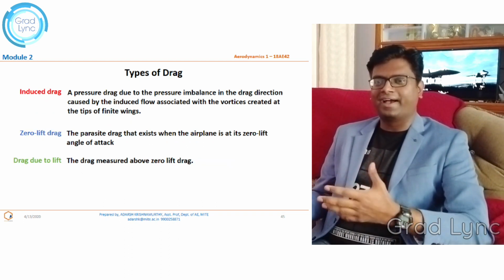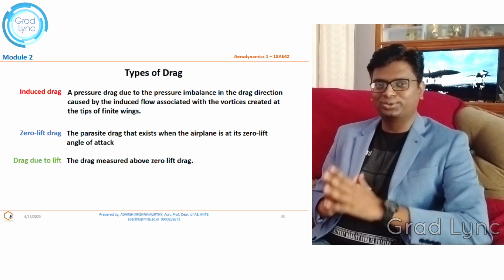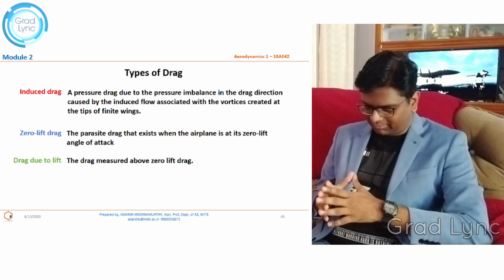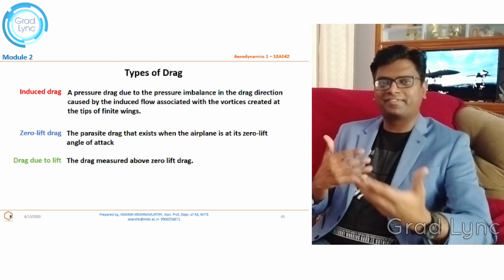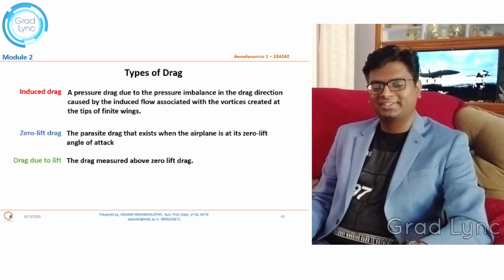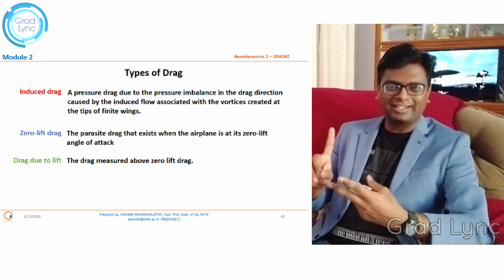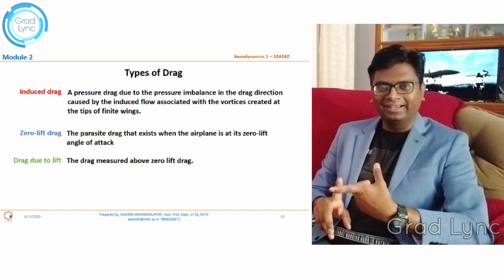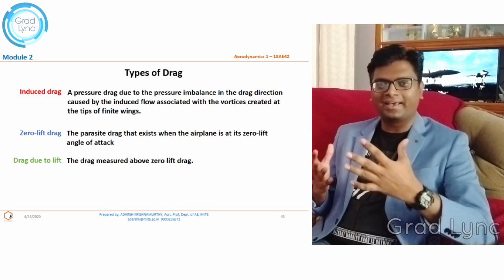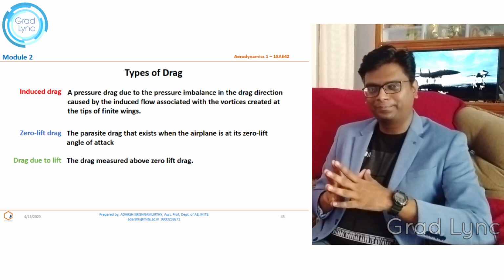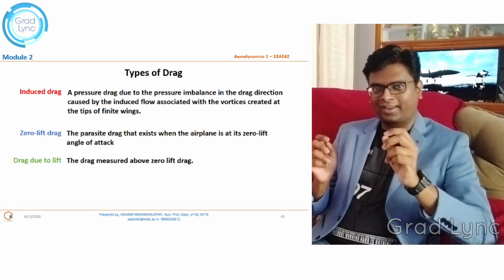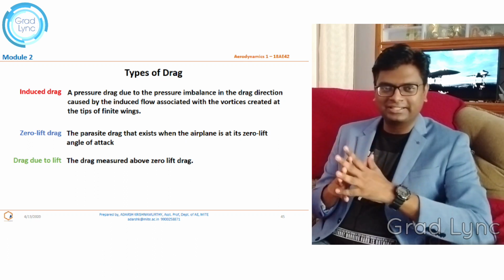Moving on, we have a very important drag called induced drag. Now most of you have heard about it. Let's discuss what it is. When I talk about a 3D wing, we have discussed the different types of wings when we discussed the wing planform geometry. What are the types of wings we have? We have 2D wing as well as 3D wing. A 2D wing has a span that varies from -infinity to +infinity, whereas a 3D wing has a finite span. When I say 3D, that means the air can flow in all three directions across the particular wing.